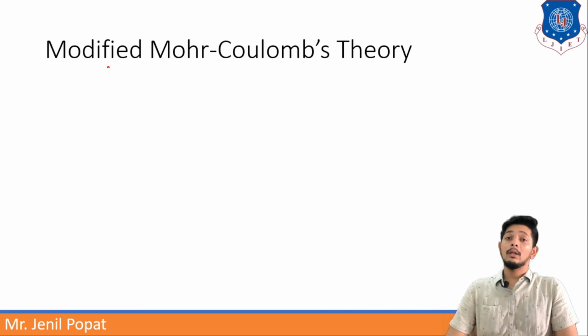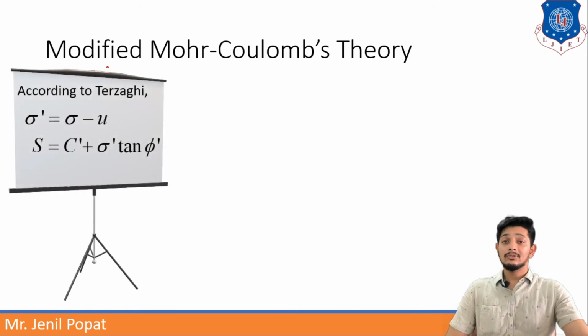But according to Terzaghi and our understanding from the chapter soil water, we can say that the normal stress is governed by effective stress, not the total stress. So we can say that the shear strength will be governed by effective stress, not the normal stress. So we can take sigma dash is equal to sigma minus u from the chapter soil water.